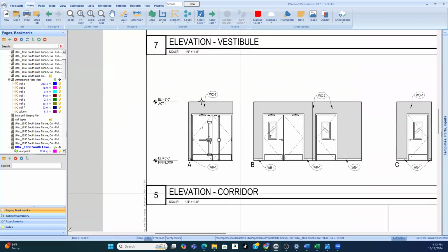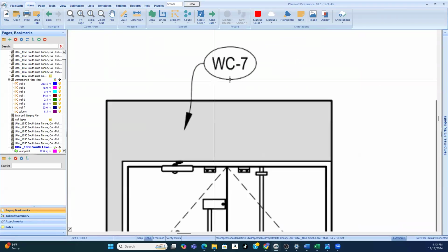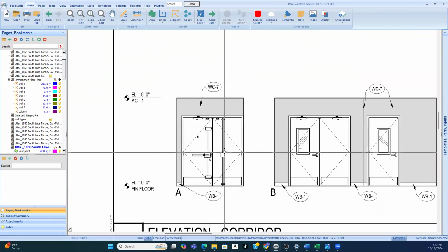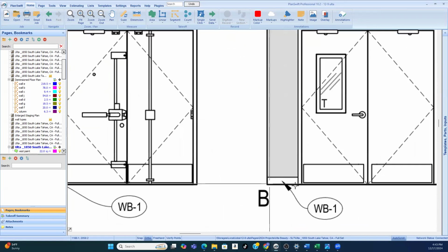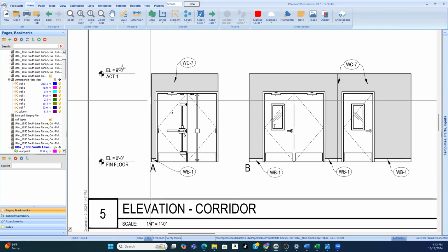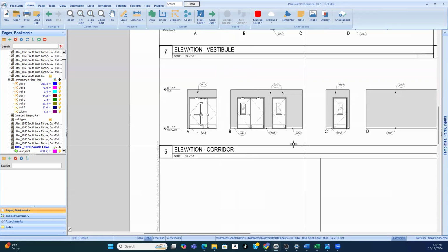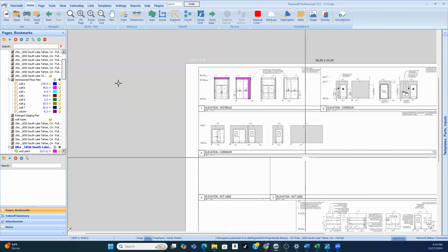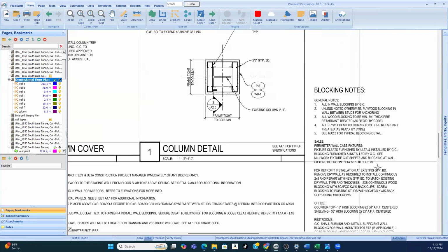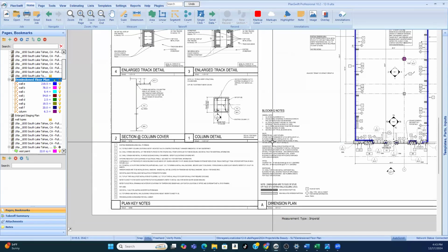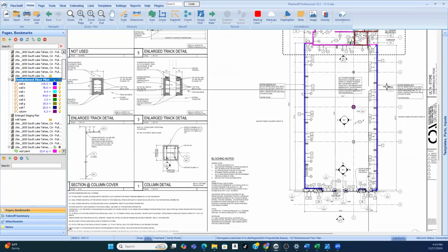Okay, so the corridor now, I know I have wall covering number 7. So I'm the finished person. I need to determine how many square feet of that do I have. And I can use this as well to determine how many linear feet of wall base. Okay. So that's an elevation view. But what it's not giving me is, I'm going back to being the framer and I need to know the height of my walls. Okay. So unless it tells me somewhere, I need to find out what the height of my walls are.